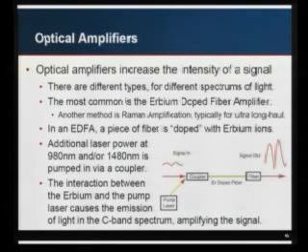What you do in an EDFA is there's a piece of fiber that's doped, coated with erbium ions. You take your signal in and you have what's called a pump laser. The pump laser works at different frequencies which are not the signal you're trying to transmit, in this case either 980 or 1480 nanometers. You pump that laser power into the system. That laser power, combined with passing through the erbium, excites the signal that you're trying to amplify and makes it brighter, and then on the way out you filter out the laser that you just pumped in. So now you have a much brighter signal than what you started out with.